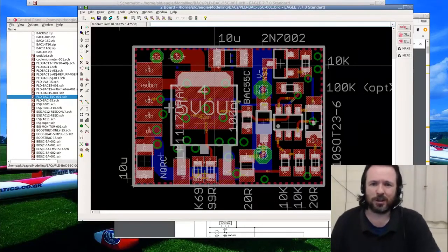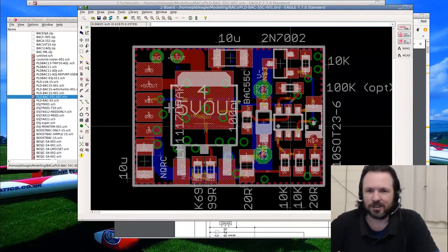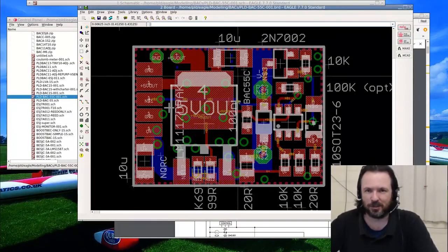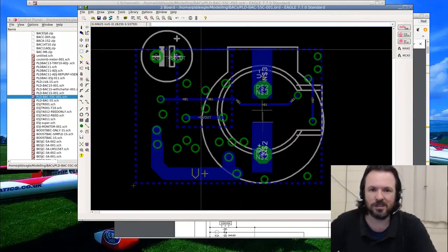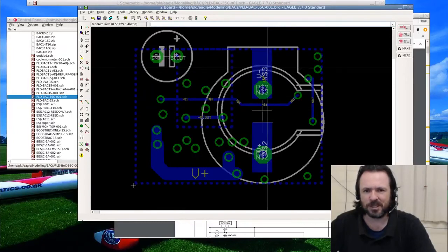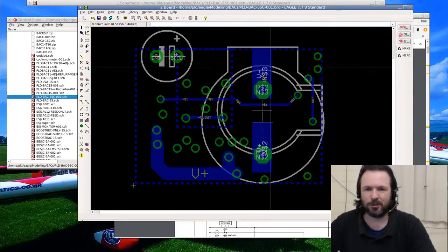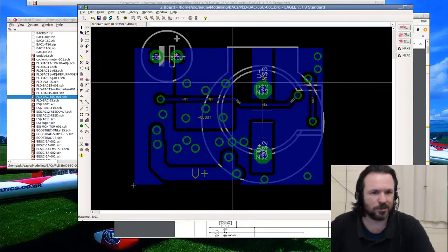Well, this was pretty much where the refinement finished up. I've violated so many spacing rules here, but it does the job. I have to pre-flash these controllers before I put them in, because there's no practical way of doing it while they're in there, unless maybe you've got a pogo board or something like that. So that's the component side. Then this is where the buzzer sits. I've got different types of buzzers, a pin-through one and a surface mount one. I used to have a 4-pad one as well, but in the end I didn't go for that.